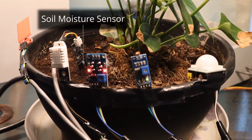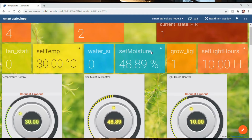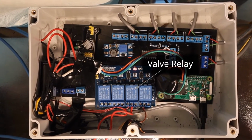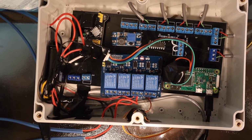Similarly, the supply of water can be monitored and regulated. As seen, the current value of water level in soil is around 48%. If the set value for water is increased to 63%, then the water valve will be turned on. The water valve will turn off once the required moisture level is achieved.